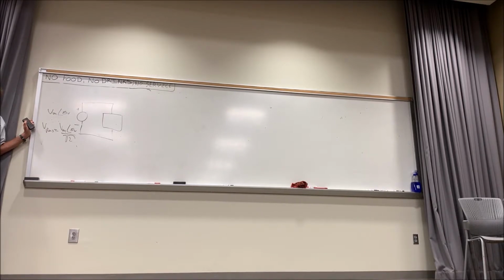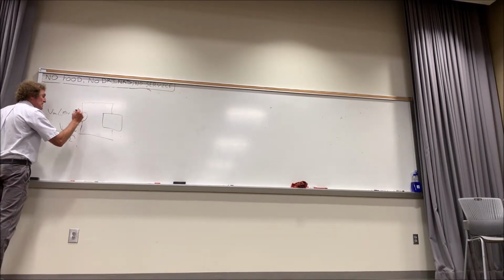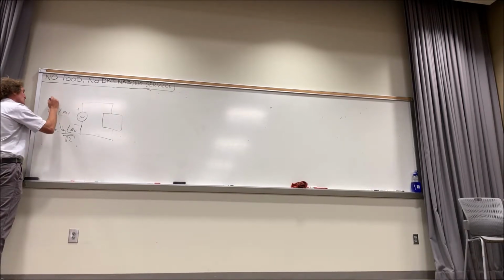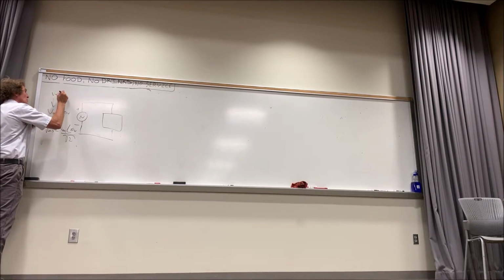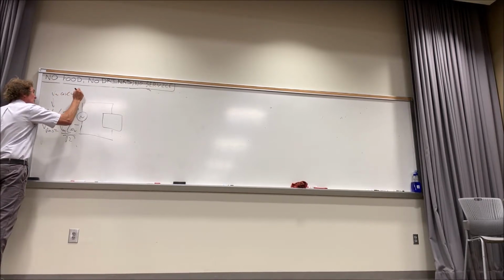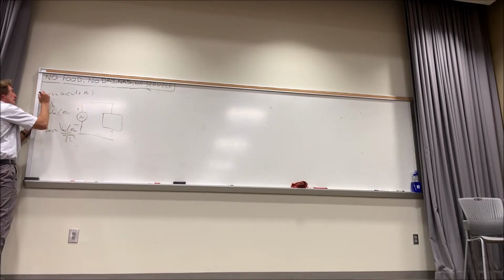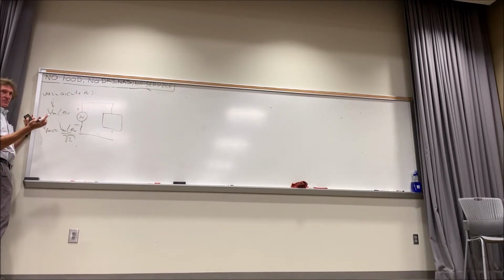This is a relationship between peak, or magnitude of the voltage, and the RMS value of the voltage. This is assuming steady state, something that's varying as cosine and sine. Everybody got that? So if you wanted the actual one, it would be Vm cosine of omega t plus theta V, the actual voltage here, V of t. I'm just trying to tell you that's what we look at.